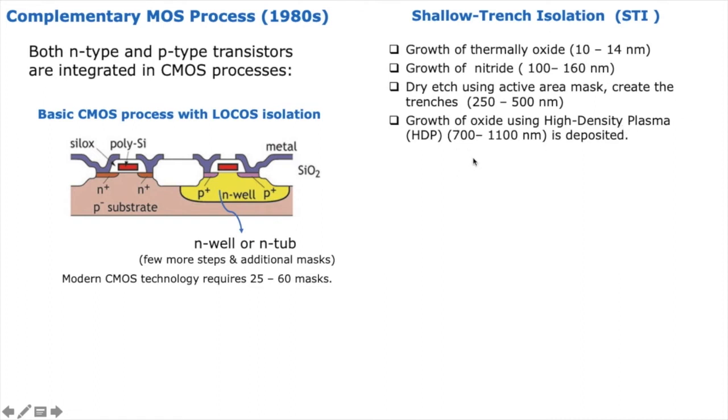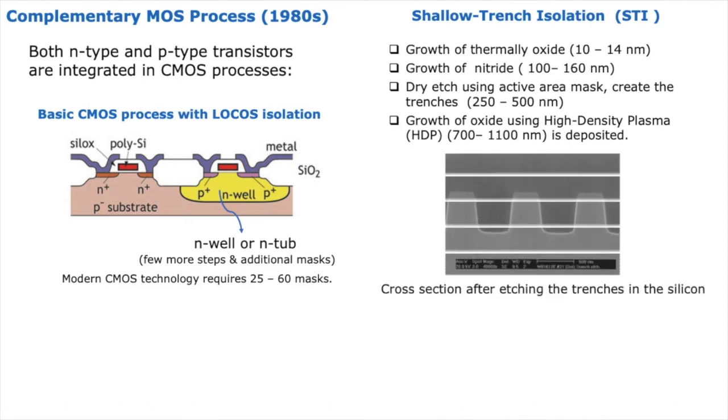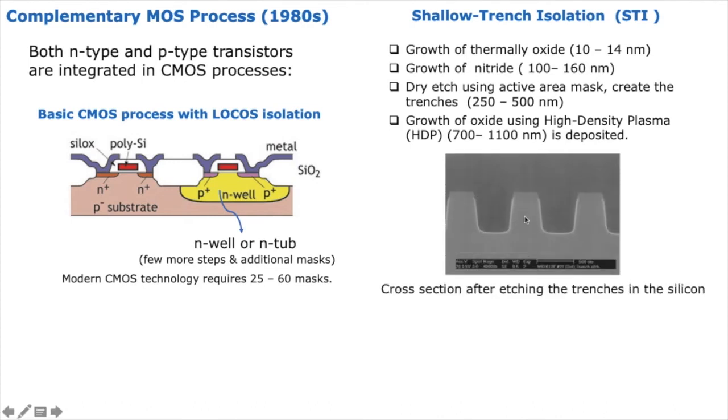So you can grow a very thick layer. This is basically the trench that you make. You first mask it and then you etch out, then you get this kind of trench, right, which is around something like 300 to 400 nanometer thickness. And then all you do is that you oxidize, right?